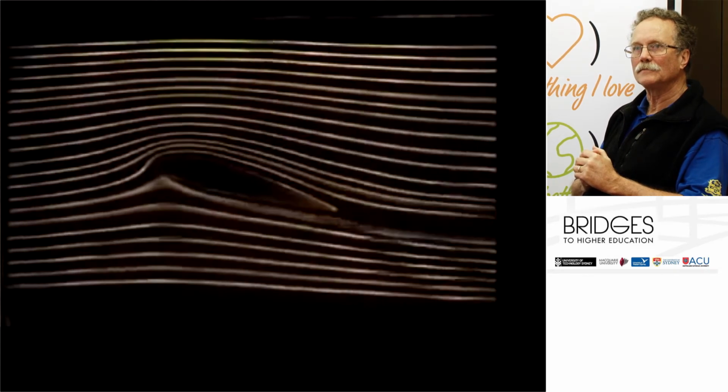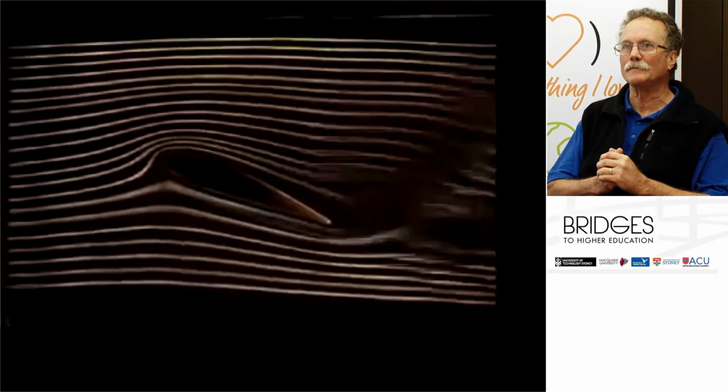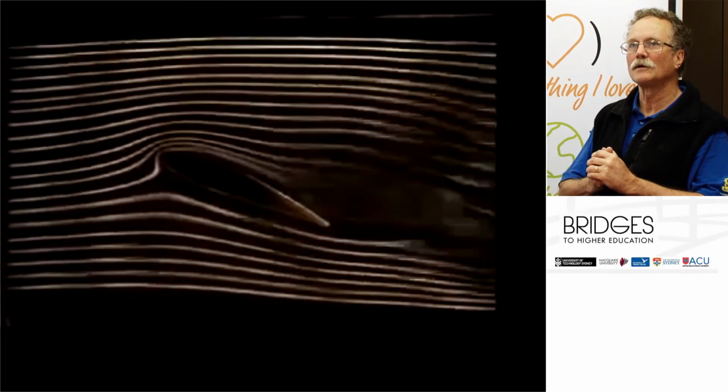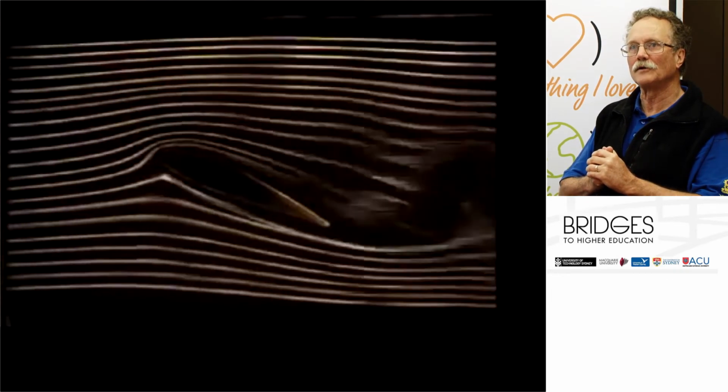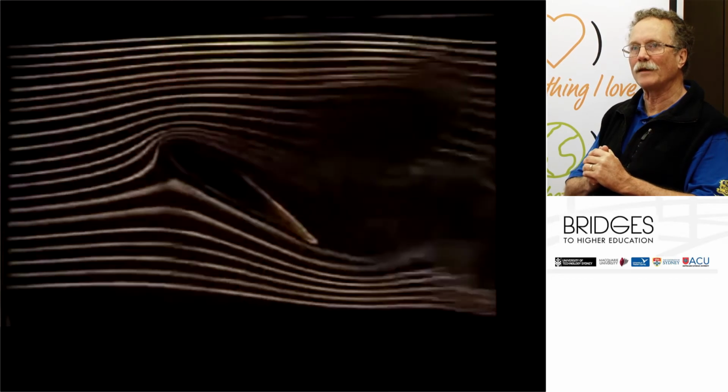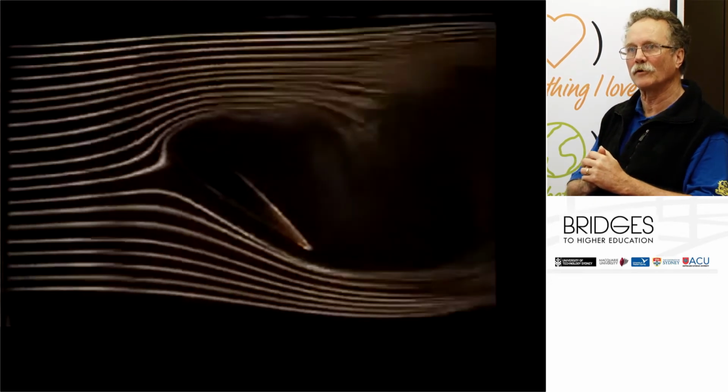But again, there's a limit to what you can do with air. It will eventually tear off the top, separate from the aerofoil, the lift will come down again. And with that big high pressure at the front, that produces a very big increase in drag.